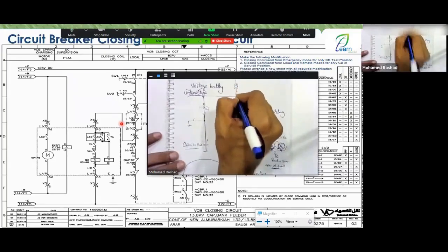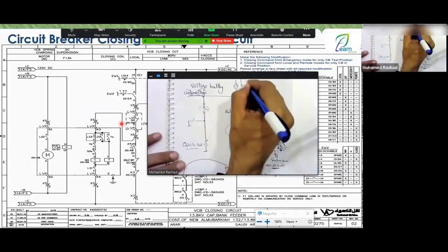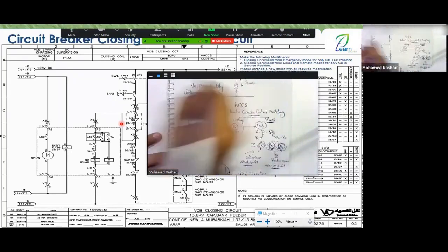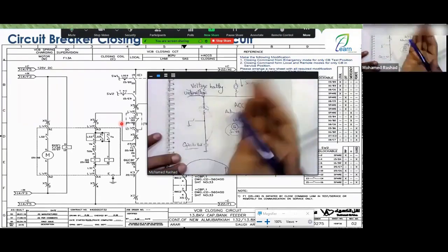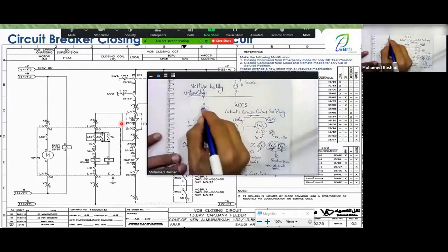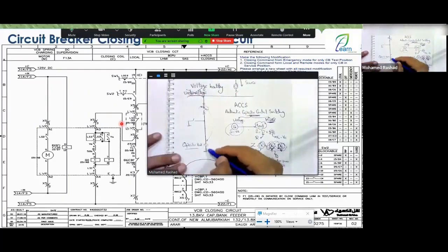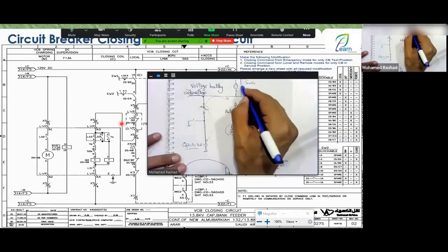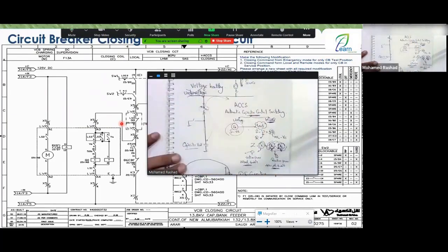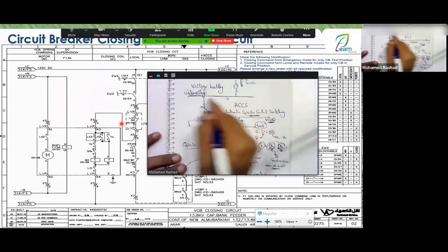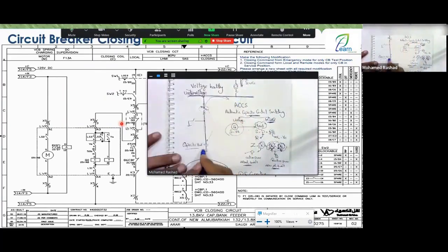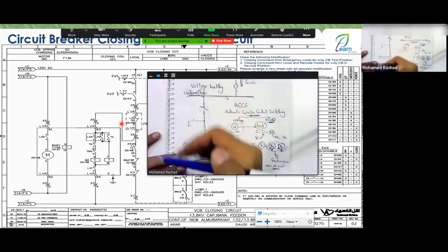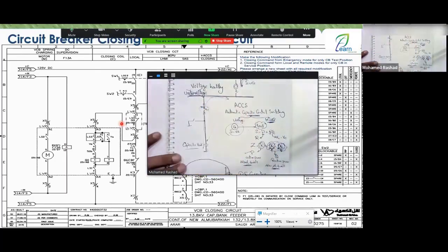Of course, for me, this is my source. So it measures the amount of megavar, and if it finds it drawn above a certain limit, it automatically connects the capacitor bank in this breaker to supply the reactive power. This way, the reactive power drawn from the transformer becomes slightly less, and the quality here returns to being correct. Or it measures the voltage present here on the bus bar. If it finds it low, it connects the capacitor bank, because this means it decreased due to an increase in active power. So it compensates for this again. This is the idea of the capacitor bank I have.